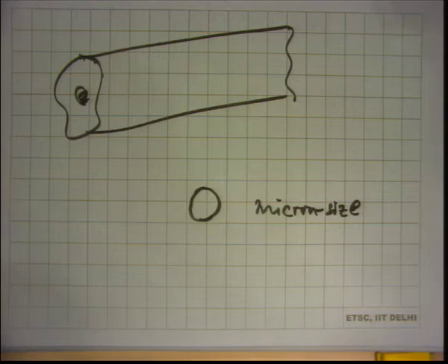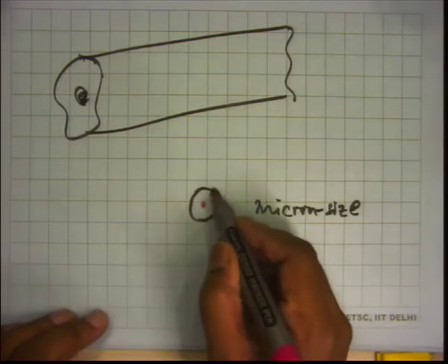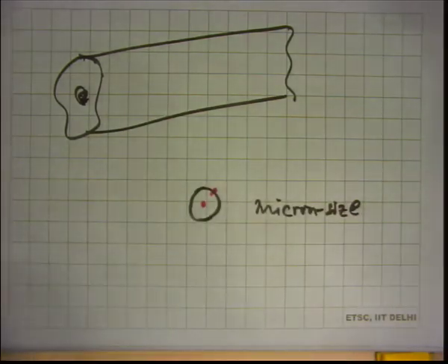The diameter of your hair is about 70 micron. Okay, so it's less than 100 micron. So it's something like that. So such a small size. If you have such a small size, we do not expect major temperature gradients in that. Right? So we can say that in a micron size particle, the temperature of the center and the temperature of the surface are going to be somewhat the same. Well, it's a good assumption to say that the particle at all points of time remains at a uniform temperature.